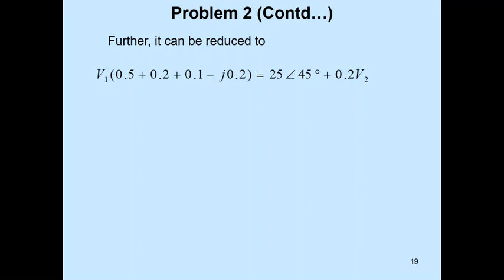The voltage across 2 plus j4 is nothing but the nodal voltage V1, so V1 must be equated to 0, and then we can find V2. Because in this equation two unknown quantities are there, but the given condition is that the current flowing through 2 plus j4 is 0, meaning the voltage across it is also 0.